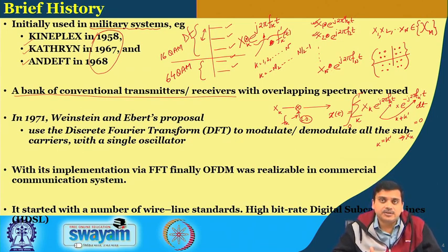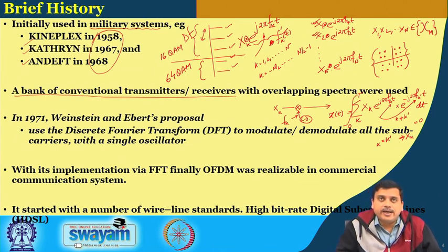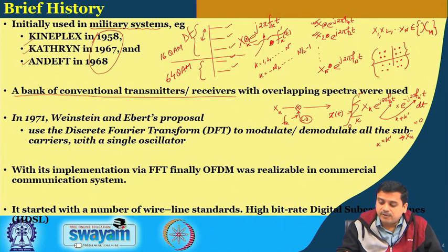So, this is a basis function. So, we have n basis functions, the codes, if they are orthogonal, they are again n basis functions, and at the receiver one can think of either a matched filter operation. I mean, here what you see is the correlation. So, when you implement the matched filter as an impulse response, you convolve.